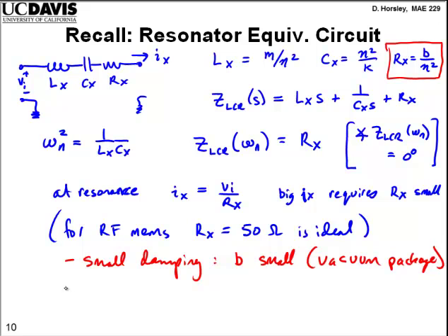The other thing we can do is basically make eta big. Large electromechanical coupling. Okay? And if you remember, let me make a new slide for this. So the equation for eta, right? Eta is equal to dC/dx times the bias voltage. So big eta requires Vp should be big, and dC/dx we want to maximize.